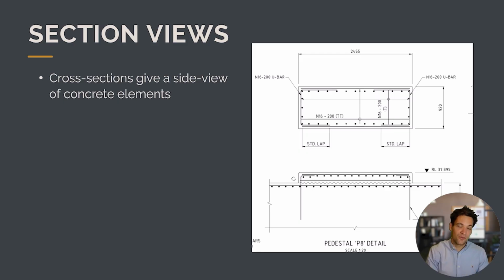The CJ note refers to a construction joint, that there's a joint between the two slabs. It helps us to better understand that in the vertical, the steel reinforcement coming out of the page, that's a starter bar from the slab below. They're around the edges, and we can see that there's a grid layout showing N16 200 in both the X and the Y direction.